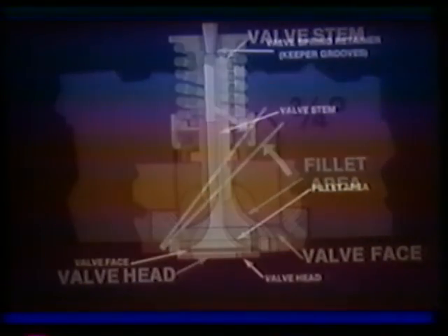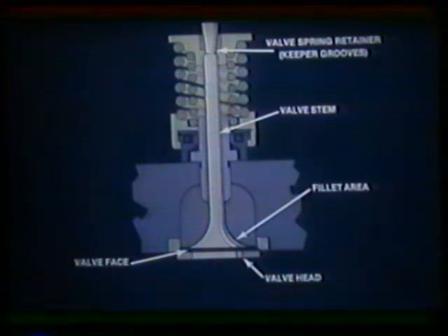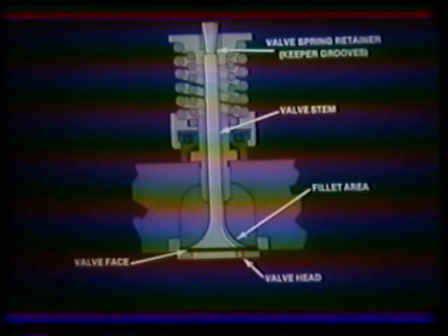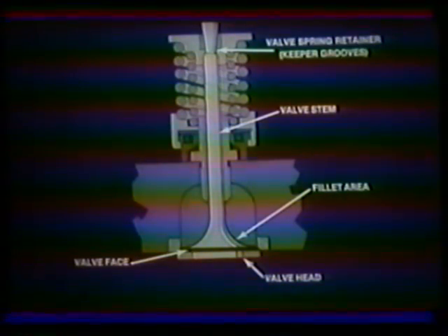Other parts of the valve mechanism are the valve guide, the retainer and spring, and the valve rotator. The valve guide is inserted into the cylinder head and does exactly what the name implies: guides the valve as it moves up and down to keep it steady. The valve spring pushes against the rotator to hold the valve closed and create the sealing action. A feature of Caterpillar engines is that most are equipped with valve rotators. This simple device turns the valves a few degrees each time the valve is opened. The rotator increases valve life.